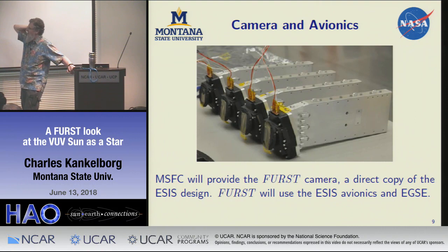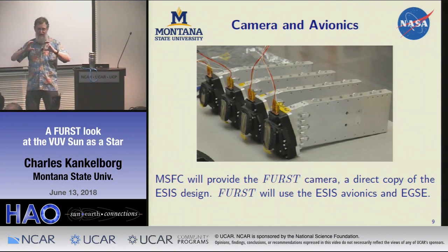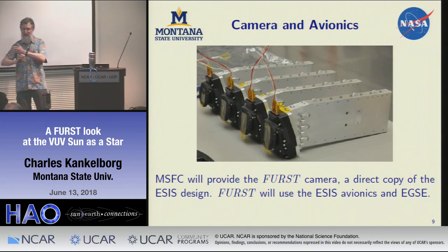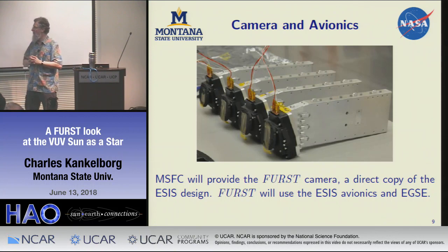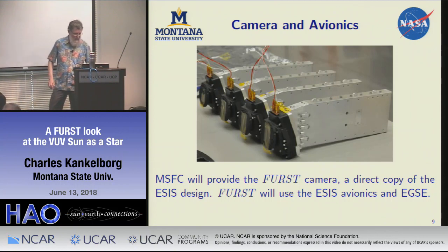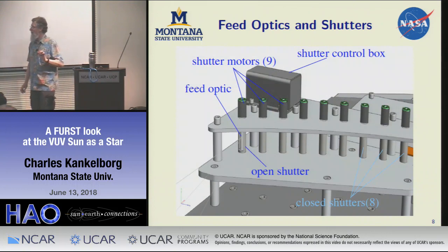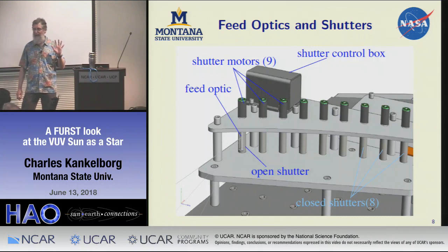But the beautiful thing is that since we orient our frame transfer CCD so that we slide the image off of it and under a mask in a direction perpendicular to the dispersion of the grating, so perpendicular to the wavelength axis, if there's any smearing at all, we smear along the spectral lines. So in effect, it doesn't change our spectral resolution, right? It's essentially perfect. So what that means is between these and these really fast little shutter motors, we can observe practically 100% of the time. We only get 5 minutes in a sounding rocket launch anyway, right? 5 minutes above about 150 kilometers, let's say, to take this data.